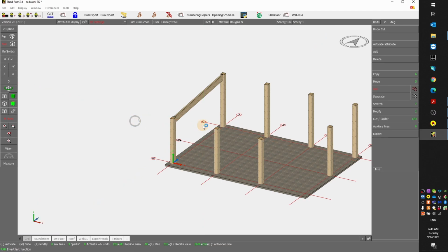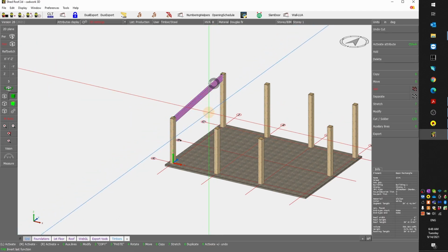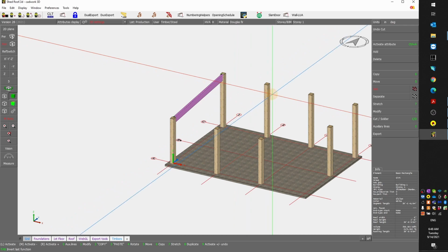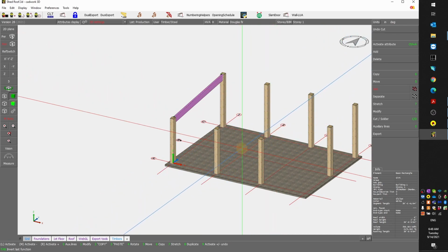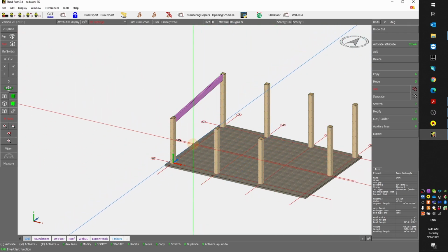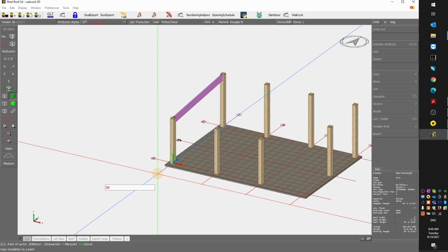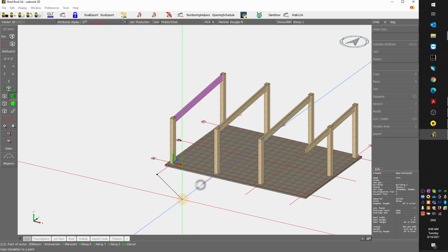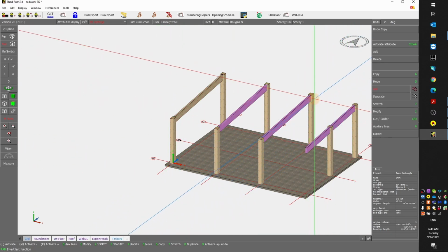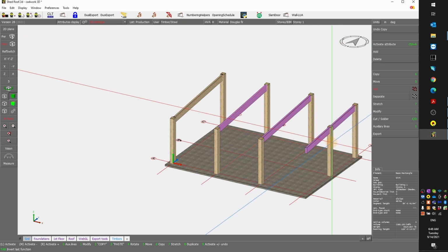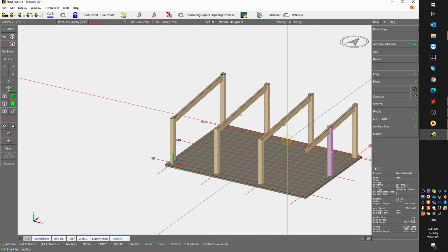So now I need to copy this guy. I'll copy it 3 times, so selected 6, 3 times using a vector, and the vector is again the same as before. Here this is going to be too long, but I'll need to adjust that column here later on.